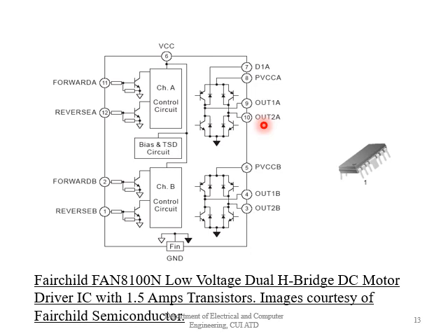So most of the time we use a feedback mechanism. Feedback is needed to achieve accurate speed control since speed varies with motor temperature and voltage. So most of the time what we do is connect an optical shaft angle encoder in order to measure the speed of the motor shaft, and then we use the signal for feedback purposes. Okay, so this was just about the IC, how we can use this IC, what's the purpose of dual H-bridge DC motor driver IC, and it is widely used in toys.